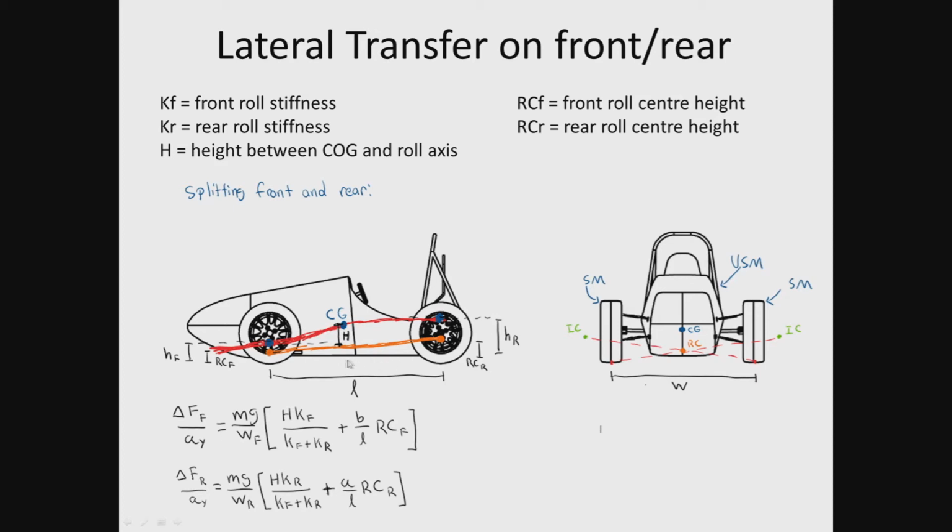And so the amount of lateral weight transfer, the equation we looked at before is for the total amount of lateral weight transfer. This divides it up front and rear, so you can independently see what does the front tire receive, what does the rear tire receive when we split up the equations. So this is more important if you're actually going to consider how much force your tires are capable of generating. Knowing these numbers front and rear independently is an important factor in knowing, are you using the full capabilities of the tire, and how much lateral force is that tire going to be able to generate.